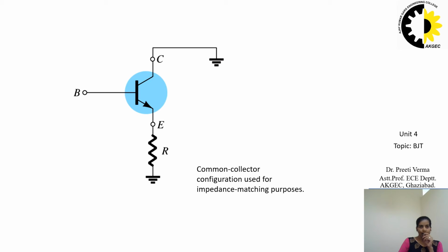It can be designed using common emitter characteristics. The output characteristics for the common collector configuration are a plot of IE versus VCE for a range of values of IB. The input current therefore is the same for both common emitter and common collector characteristics.